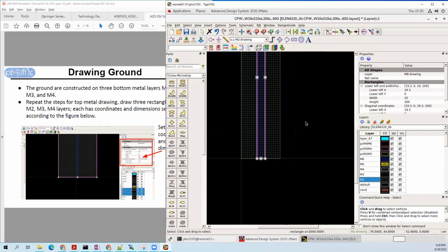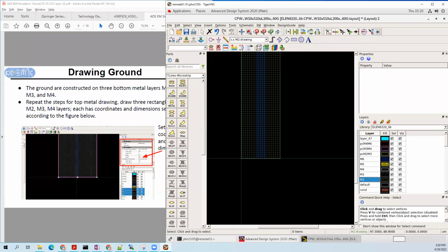So in here I design what's called a 10-10-10 coplanar waveguide. It means that the width of the signal path is gonna be 10 micrometer, and the horizontal spacing between the conductors is also 10 micron. Let me draw it. So we're gonna draw something like this. This one is the top view.